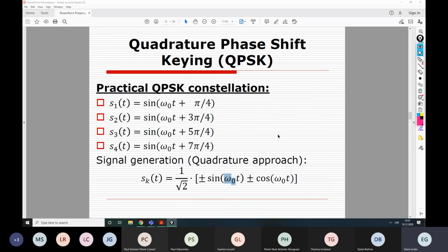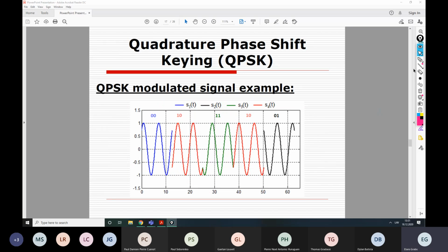So this means that actually it's half of the period later, right? So here we have half of the period, and that's when it continues. So you can observe also the phase shift. Okay, yes, so we have a phase difference here at this time moment, the change of the phase. That's natural because the modulation type is phase modulation, right? And that should have these phase changes here and here and here and so on. Now, each of these signals, as I have told, contains information of two binary symbols. And that's how the information is sent twice as fast compared to usual binary phase shift keying.